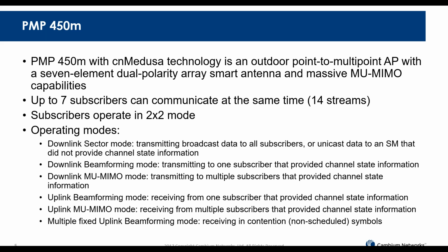For this reason, the access point needs to be able to receive from all the directions. And this mode is called multiple fixed uplink beamforming mode, because the access point is creating multiple overlapping beams to make sure that it can receive from all the directions in the sector.